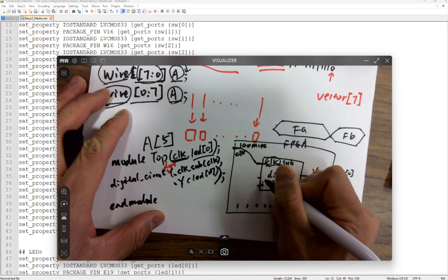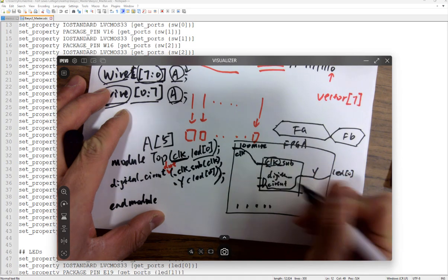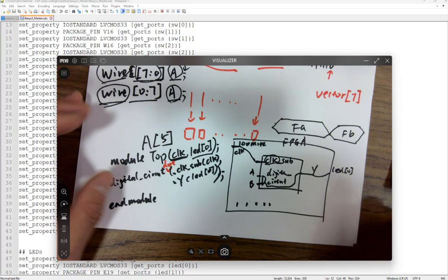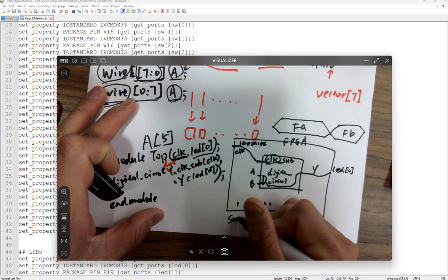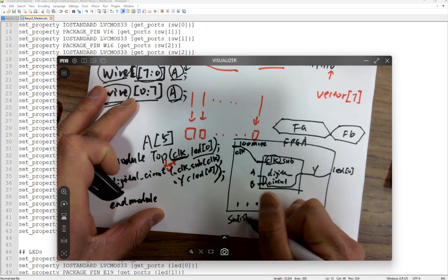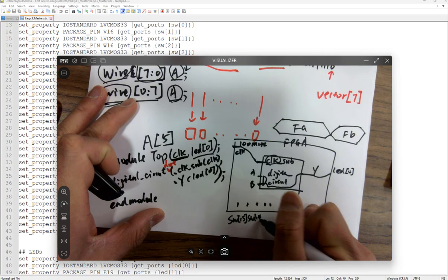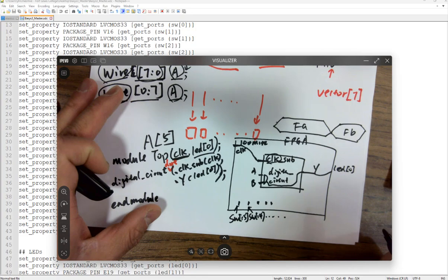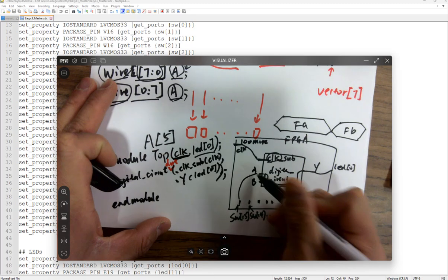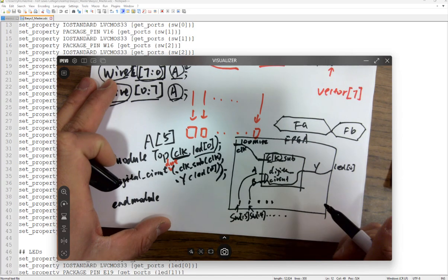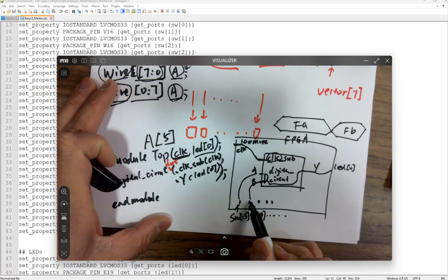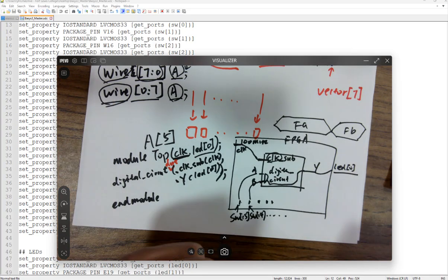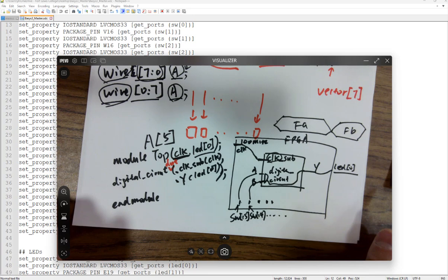If you have an AND gate here, connect to output is AB, right? A, B, Y, AND gate. This is switch 15, switch 14, so on and so forth. So this guy and this guy. It could definitely make connections over here. So you can use 2 switches as the inputs and 1 LED as the output. You can form a little AND gate and you can demonstrate on the FPGA board.